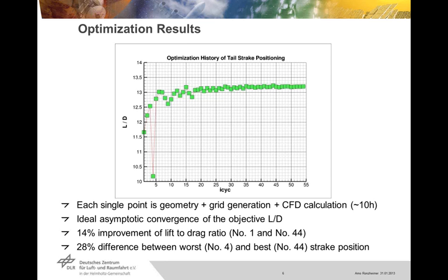Therefore, it is very easy to open the corresponding CFD results for deeper analysis with Tecplot Chorus directly from this history plot. And the sorting function in Chorus helps you to find the minimum and maximum values immediately. This study was performed 2 years ago, and here I used the Tecplot probing function to find this. I think we'll see much more useful features in the following live demonstration.